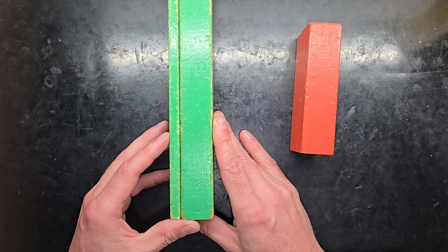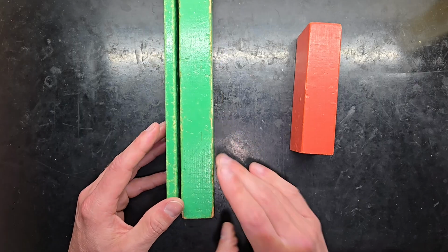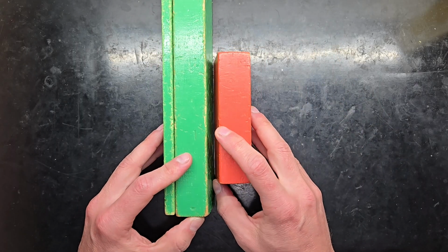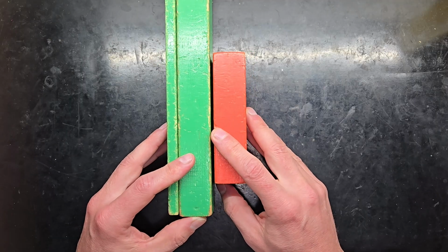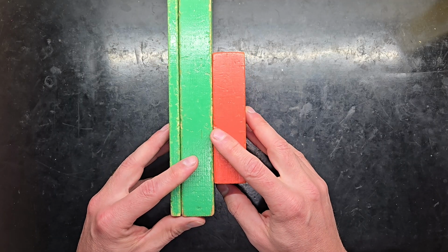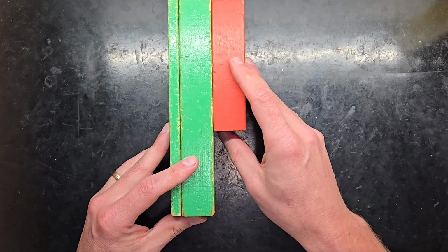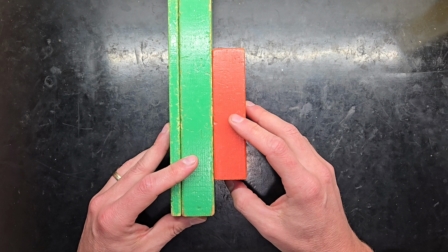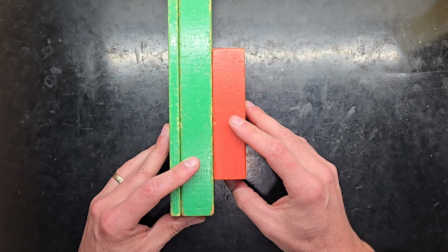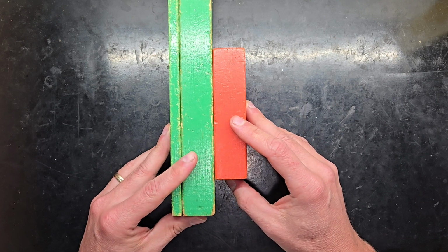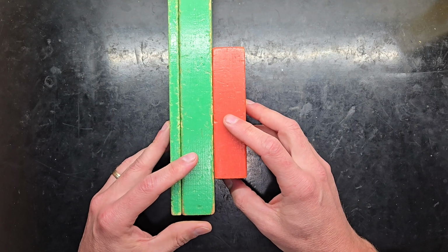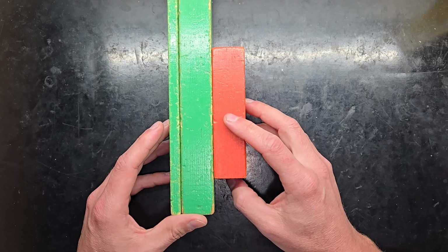Adhesive wear can also take place between similar or dissimilar materials. There, at the surface interface, you can have atomic bonding or cold welding that removes material from one body and transfers it to the next. When that material is removed, it is possible for that cold welded or atomically bonded material to then break off. So your adhesive wear can then lead to abrasive wear.